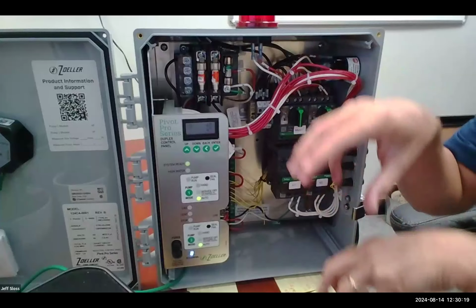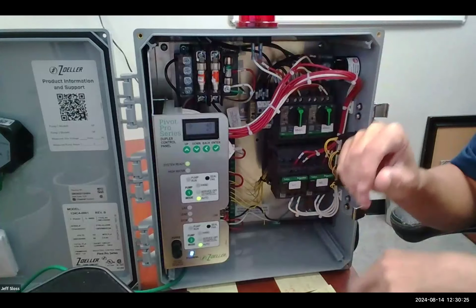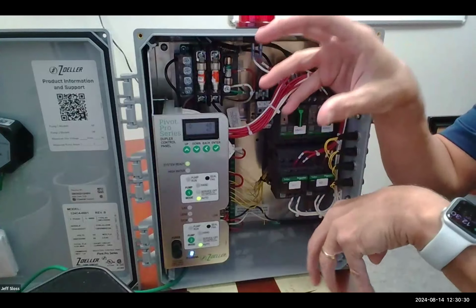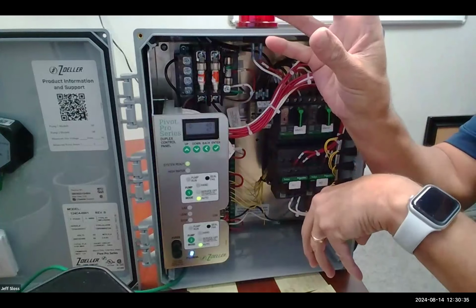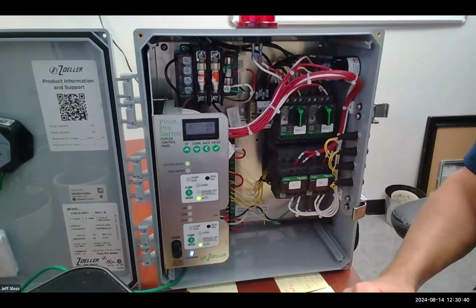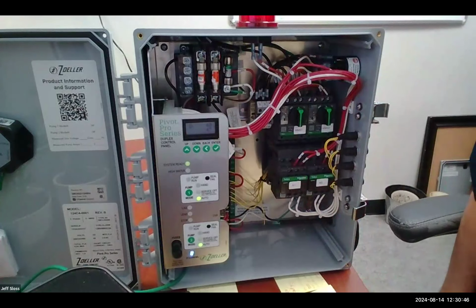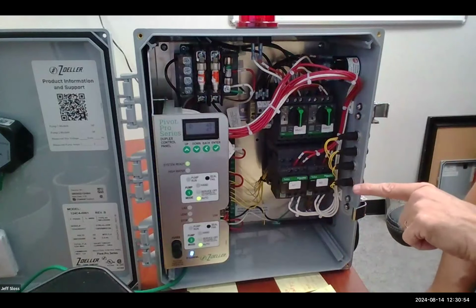Yeah, the pump will just continue running, right? No, the pump turns on? No, if you do this on the old panels, no pump is running, because the stop float, it's a relay-based system. There's no smarts to it. So this has to be up and this has to be up for a pump to turn on. If only this is up, your pump is not going to turn on. And most people don't realize how susceptible they are to a big $50,000 lift station not running properly because of that one problem. Now I'm just using this as one example. There's many examples for float faults, but let's just use that example.